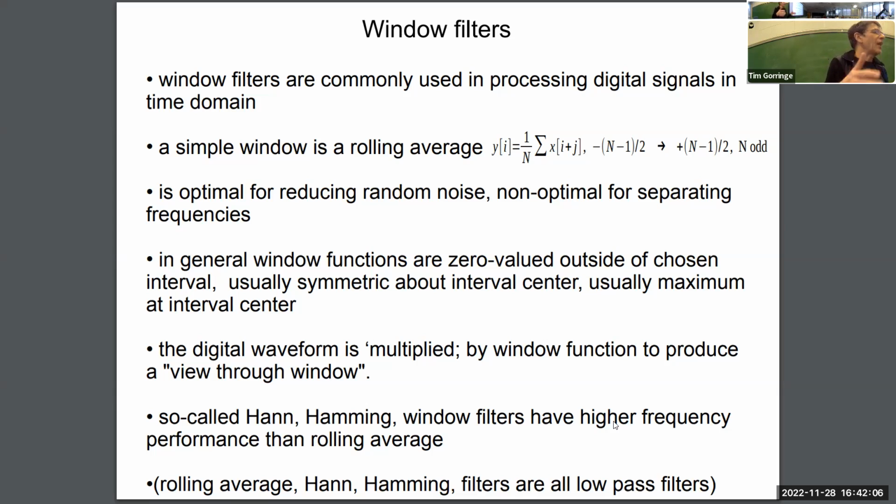So if it was an average of 1, you'd get exactly a copy of what you put into the input coming out of the output. If it's an average of 3, for example, so maybe the target sample and then a sample earlier in time and later in time, you get an average of those 3 samples. And you could imagine having averages of n samples, and that's your rolling average.